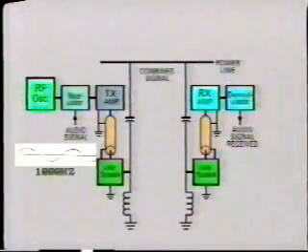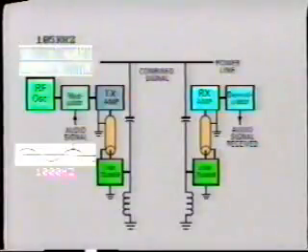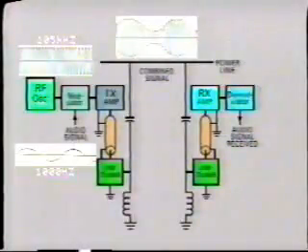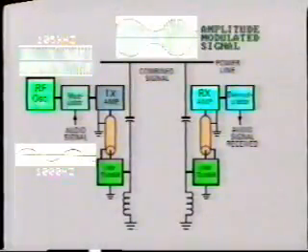Suppose, for example, we wish to transmit a constant 1,000 Hertz signal, perhaps for alarm purposes. This audio signal is superimposed on the high-frequency carrier signal, say 105 kilohertz, and modifies the amplitude of its wave. This is known logically as amplitude modulation, AM.